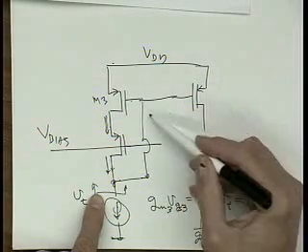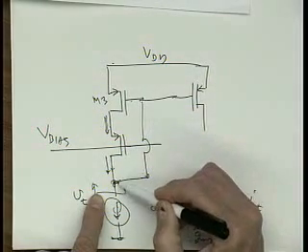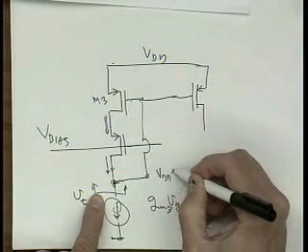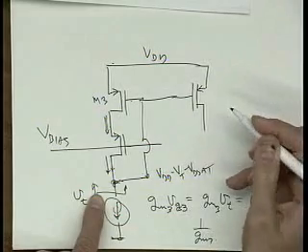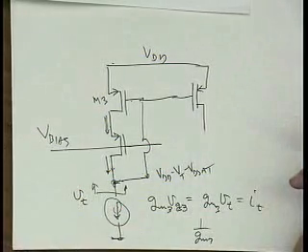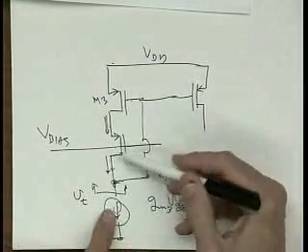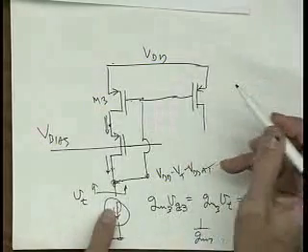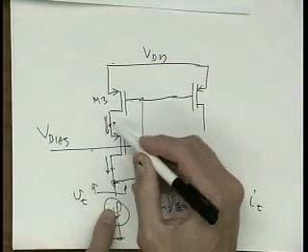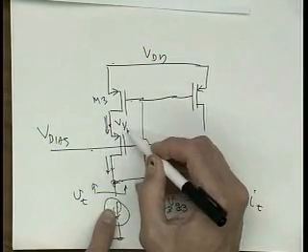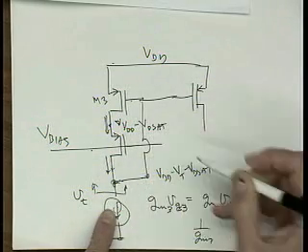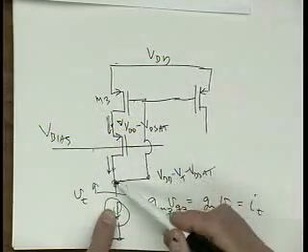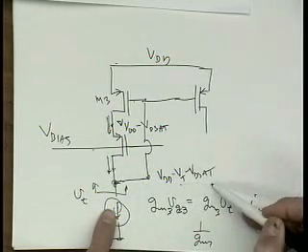But it's handy, because this voltage now sets the voltage on this node at VDD minus VT minus VDSAT, and that's just what we'd like. That's plenty of voltage. Let's say, because of this bias, this is set at VDD minus VDSAT. At this voltage, it's VDD minus VT minus VDSAT.